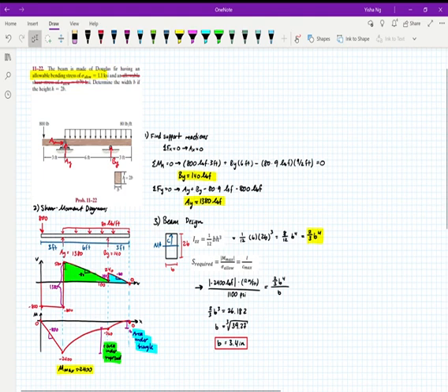From here, I have a rectangular distributed load, which is pointing down, which means it's negative. That means my slope is going to be negative. It's going to be negative 80 because my distributed load has a magnitude of 80. So from 580, I'm going to have a slope of negative 80 over the course of 6 feet. That will take me from 580 to just 100.